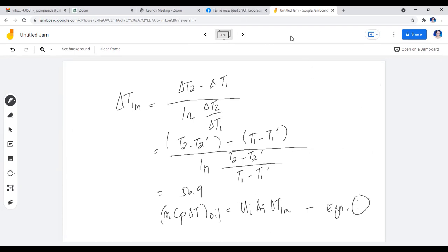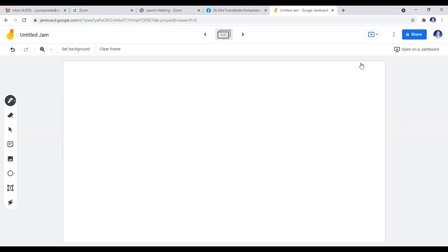So if we would do that, the mass flow rate of the oil is 3,630 kilogram per hour, your Cp is 2.30, and the temperature difference is 371.9 minus 349.7. The value of this Q actually is 51,490 watt.